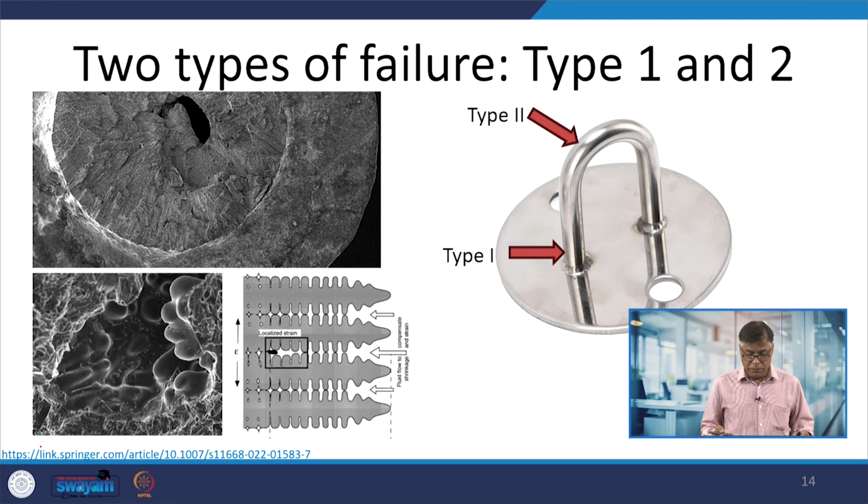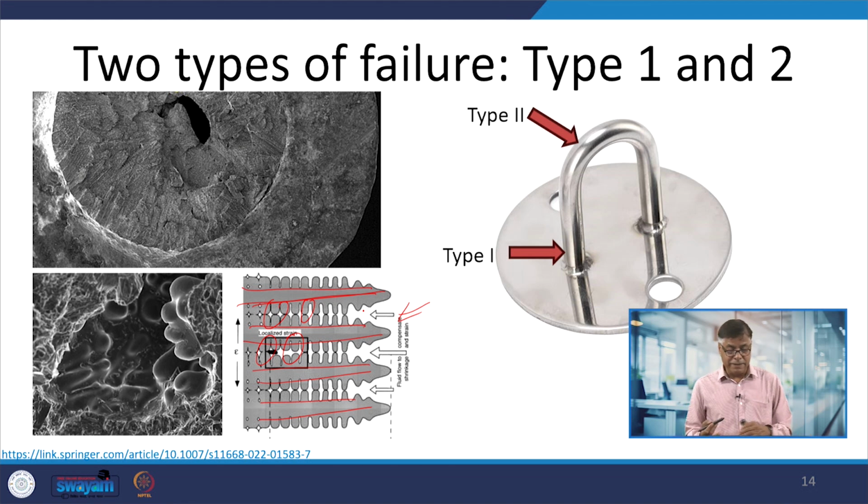How does this happen? When solidification is taking place, there will be dendrite formation on both sides, but when the dendritic arms start obstructing the path of flow of fluid, the spaces between the interdendritic arms are not filled in, and that in turn leads to the formation of shrinkage porosity in the casting.